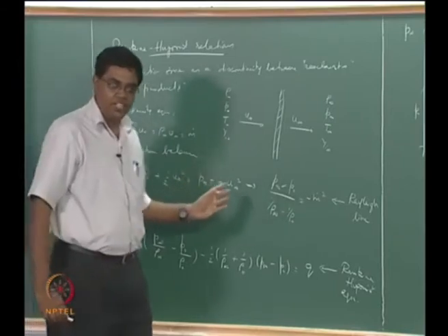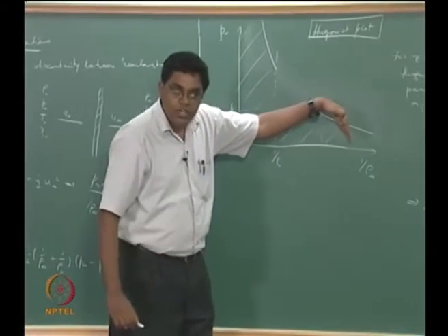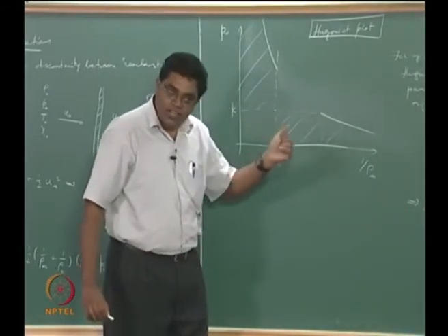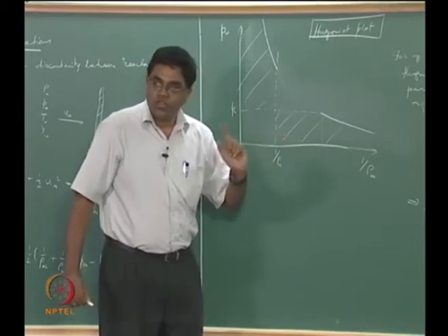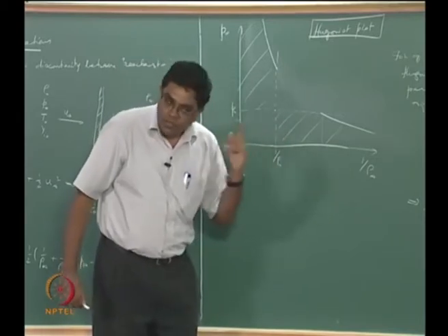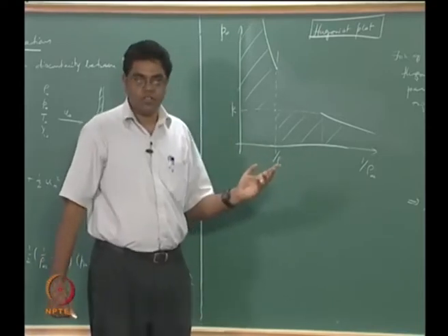So you had a heat addition, all right, that is the reason why the Hugoniot is shifted away from the origin in the first place. So you had a heat addition, correspondingly you had a temperature rise, but you didn't really have a wave that was moving fast enough, and you didn't have a corresponding pressure rise.